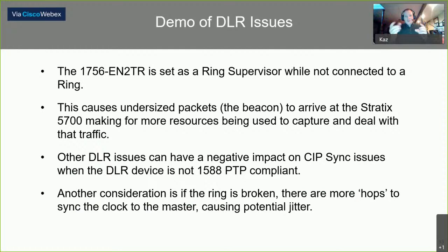and your PLC and motion is real close to the supervisor, and that gets broken, and then you've got to go all the other hops back around to that servo drive, then that could cause potential issues for syncing to the master, causing jitter.